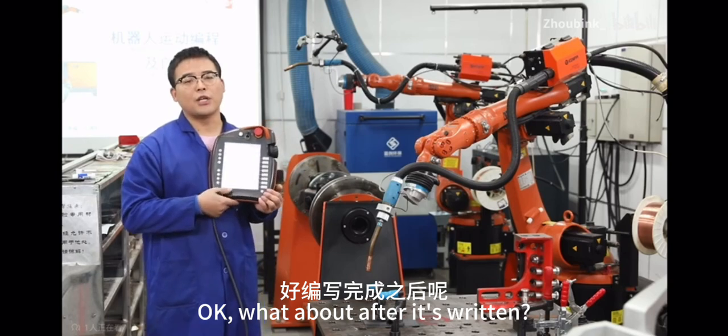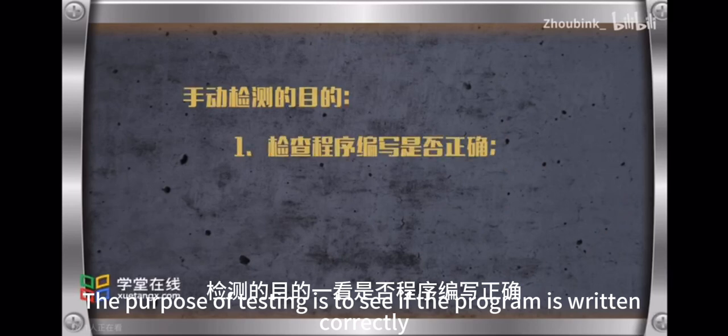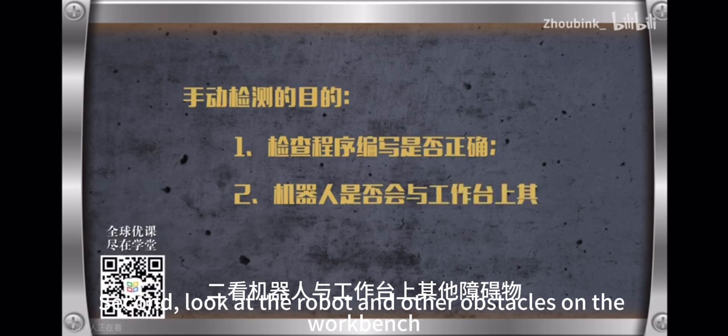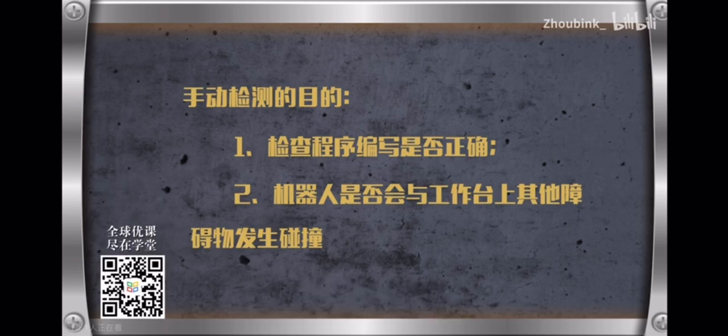OK, what about after it's written? We're going to manually check the program. The purpose of testing is to see if the program is written correctly. Second, look at the robot and other obstacles on the workbench, whether there will be a collision. So what do we do? Let's run some tests first.